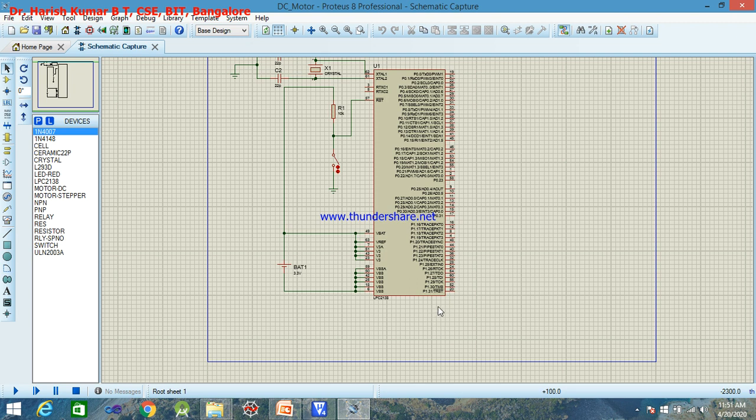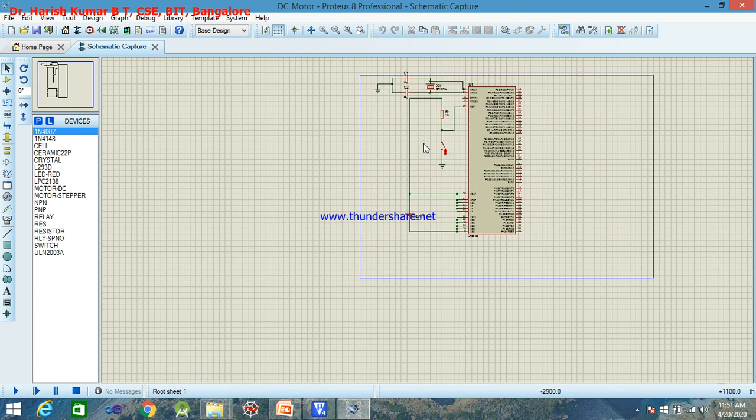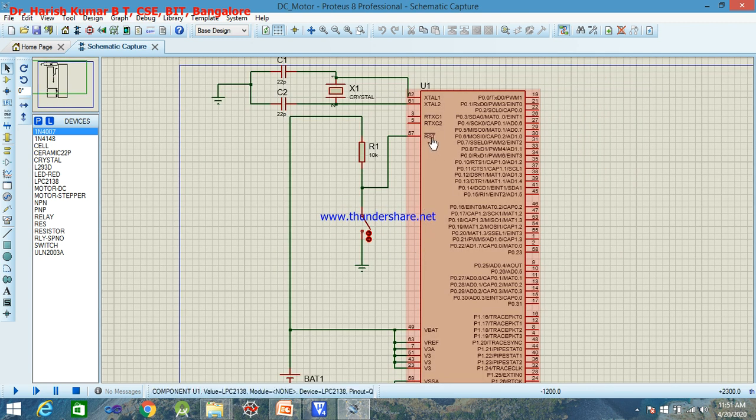So this is the power supply, because the low power controller operates with the voltage 3.3 volt, and this is the active low signal RST bar. Now it's going low, it is active, and this is the quartz crystal which supplies all the clocking requirement for the microcontroller, and you have all the port pins here, P0.0.